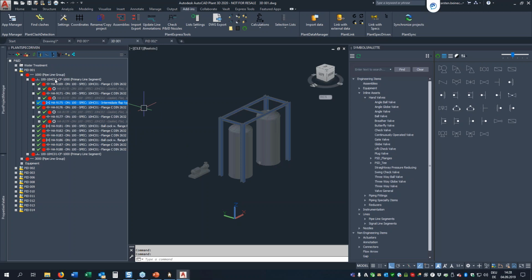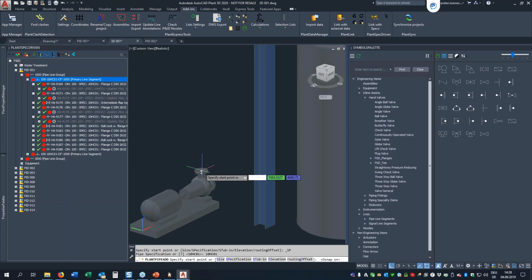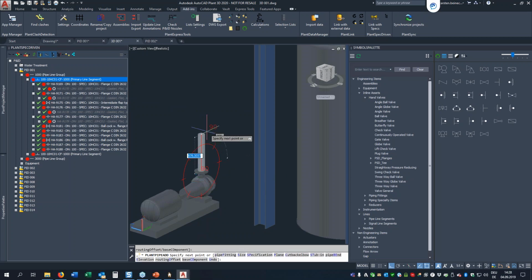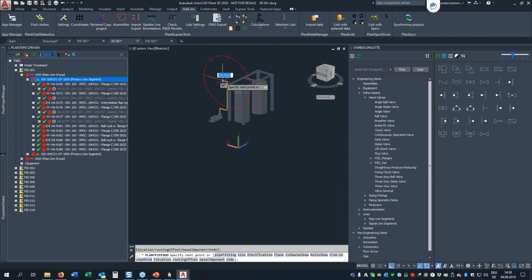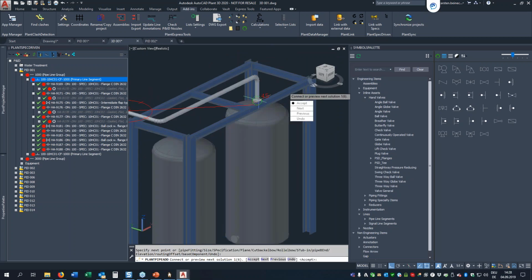So now going to P&ID because I have to hurry up a bit. So now I have this line here. I want to route that pipe or that line. So let's see, turn on the, okay. I did not use the correct note. Let's see, there seems to be some graphical issue. There should be a flange already. Anyway, so 3500. Of course, I know the dimensions by now. And let's connect here. Accept.